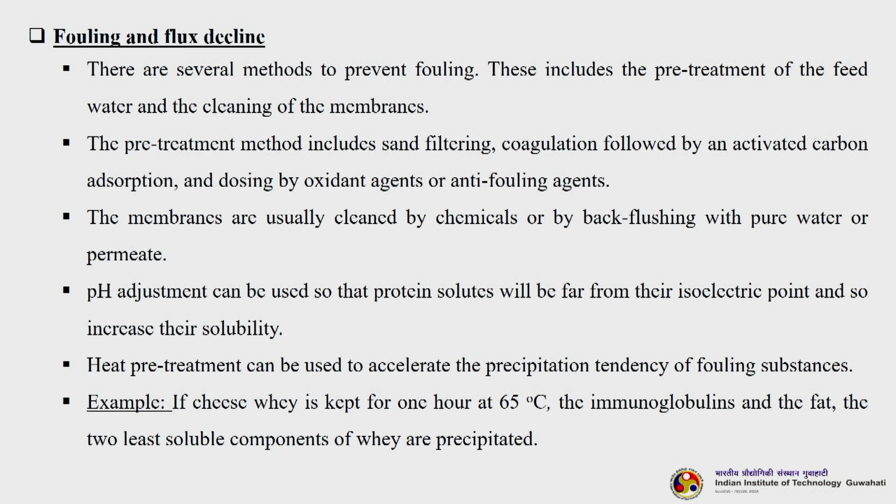It is very important if you are treating wastewater, whether it is sewage, domestic or industrial, as well as process wastewater from various industries. They contain various types of components: suspended solids, dissolved solids, heavy metals, oils, greases, and what not. The maximum of these, the TSS, suspended solids and all, needs to be removed by using a usual filter mesh or screen before it goes to the ultrafiltration system.